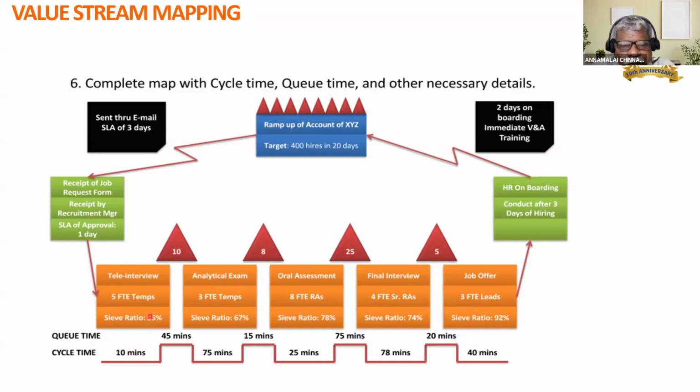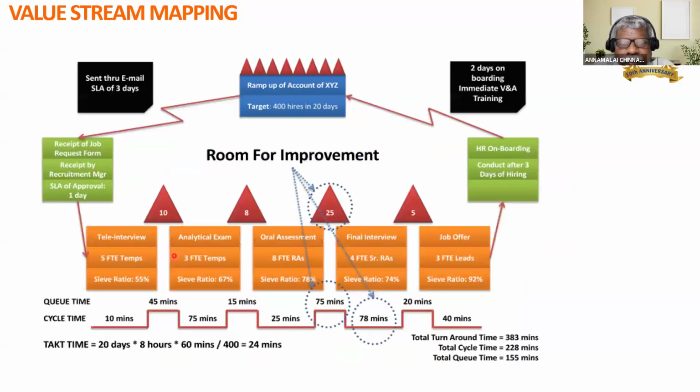And moving from this process to the next process, on average, how much time does it take? That is the queue time or the waiting time. So for each and every part you are going to produce, you capture the process time, the waiting time, the yield at that particular sub-process, how many people are involved, and the average inventory. Those are the minute details you start collecting for the process.